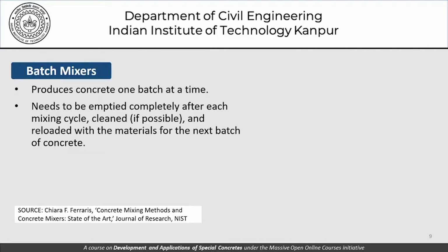So this cleaning of the mixer is something which is interesting, because whatever material remains in the concrete mixer gets added to the next batch, except if you want to argue that, well, whatever is left in one batch will also be left at the end of the second batch, and therefore the second batch will be truly the right batch, which then takes us to the discussion of what happens to the ingredients in the first batch, because parts of it are left behind in the mixer. This typically happens in the case of mortar. A lot of mortar sometimes is left behind in the concrete mixer.